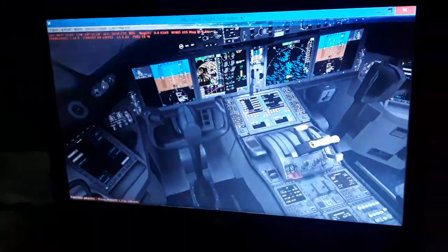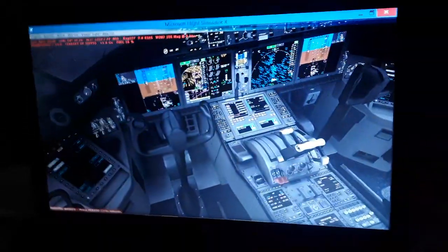So I'm going to show you now the flight controls of the aircraft using the side stick here. We control the horizontal tail of the aircraft for climb and descent using the control column, pitch up and pitch down. Also bank rolls left and bank rolls right using the control wheel. Also we have the rudder pedals. We can use the vertical rudder for making coordinated turns left and right. Also we have the rudder pedals for toe brakes and for nose wheel steering on the ground.